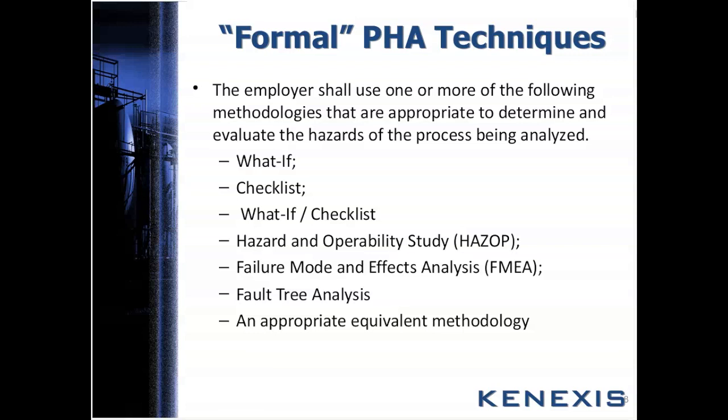So the PHA is dependent on very good judgment, and the assumptions made during the study need to be documented and understood by the team, and then the PHA is kept for future PHAs for further evaluation. Several of the techniques are more appropriate for performing general process hazard studies, usually early during the life of a process, such as the safety review, the checklist analysis, the relative ranking, PHA, and what-if.